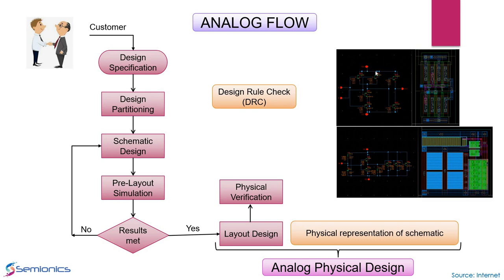So now the schematic designer has done his design, he has done his simulation, and the layout designer has done his share of the job. Now, the Foundry gives you a set of rule files and tells you that only if you follow these rules and do a physical implementation, we will be able to fabricate your design. So when the layout designer is doing his layouts, he needs to abide by the DRC rules, right?